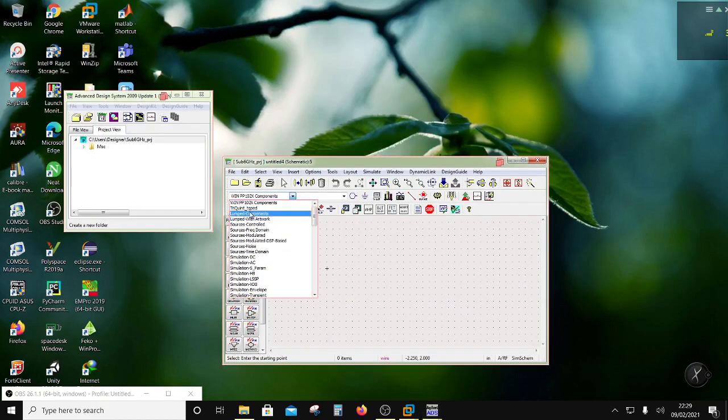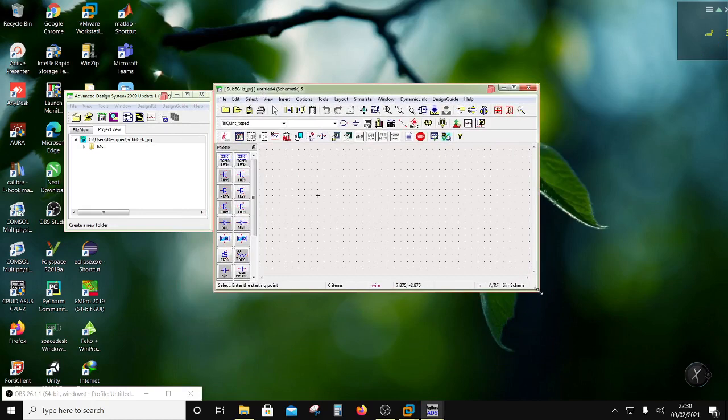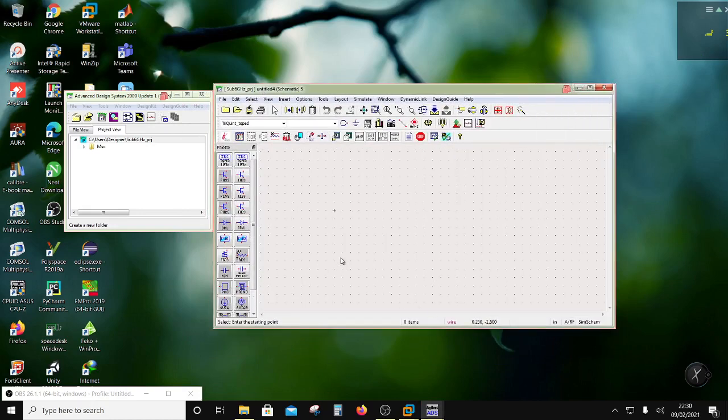I'm going to use a process which is kind of old now, almost a 15-year-old process. It's a 0.5 micron process, but this goes up to like 33 gigahertz cutoff frequency, and it has both depletion and enhancement mode devices. So I'm going to use an enhancement mode device.